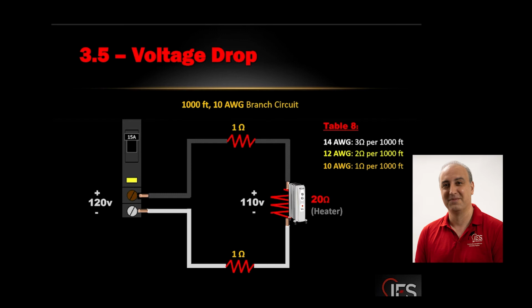I guarantee you, any system you put on 110 volts instead of 120, it works fine. Because that's the system. Sometimes we even call it 110. UL has a rule of thumb that it's usually about plus or minus 5%. So in a 110, 120 system, it's like 115 plus or minus 5%. Everybody has to design their equipment to work within that range. But as soon as you fall outside that range, things stop working.